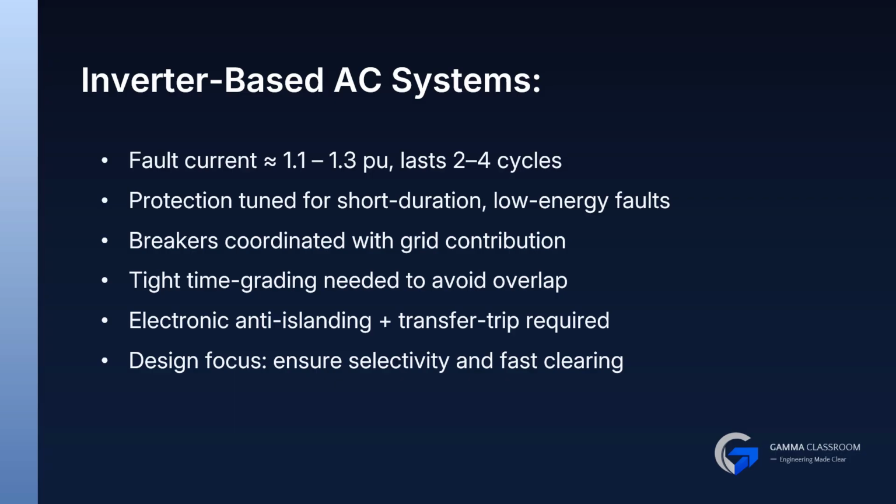Utilities also require electronics, anti-islanding, and transfer trip functions, because mechanical isolation alone is not enough for inverter systems. So the design philosophy shifts from limiting fault energy to ensuring selectivity and fast clearing.